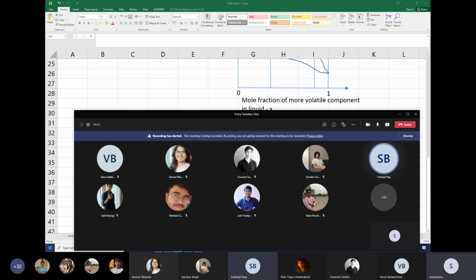What kind of solutions are the Margules and Van Laar equations used for? We use them to get the VLE data. Are you sure? Yes, sir. There was some term called gamma, and we used to find it. Margules basically gives the Gibbs excess energy, G by RT, versus x. From that, we calculate chemical potential. But they are predominantly used for non-ideal liquid mixtures. That would be the little tougher case.